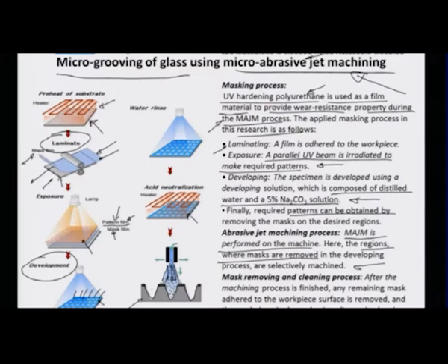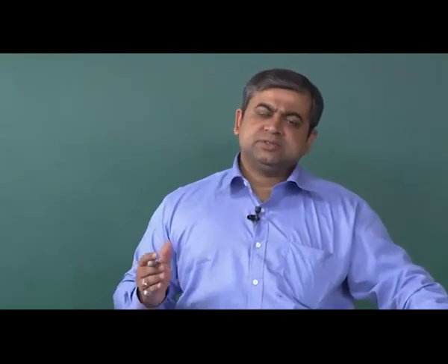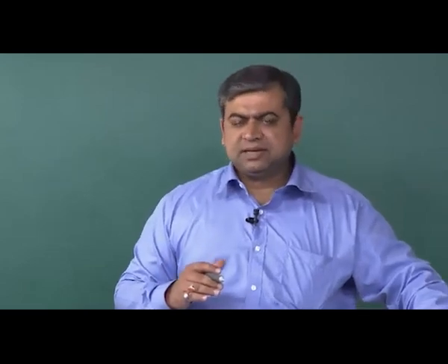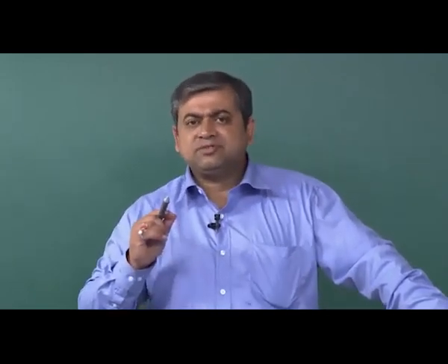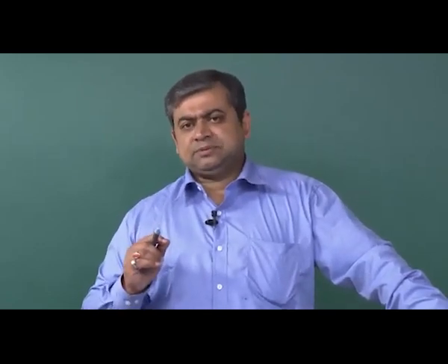There are some remaining materials of the mask which adhere to the workpiece surface, because as you know, it is laminated onto the surface, and there is an amount of pressure as well as temperature given onto the plastic so that the adherence is complete over the whole flat surface without any gap or air pockets in between. And so sometimes stiction is a major problem and the mask remains back on the parent substrate.